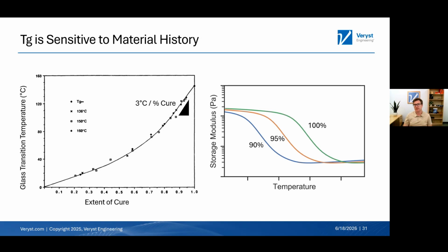The way I would phrase this is that the TG is a much more fundamental and intrinsic parameter of the material. The HDT is measured under a specific set of conditions, typically a constant load, and once the deflection reaches a certain value. It's essentially, depending on your assumptions, a criterion on when the modulus of your material drops below a certain value. I forget what that value is. I think it depends on the applied load.